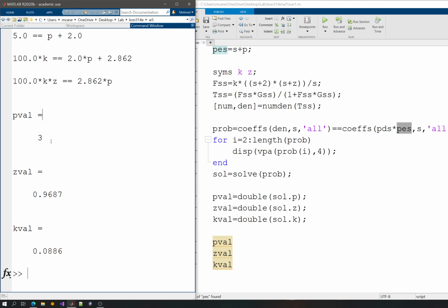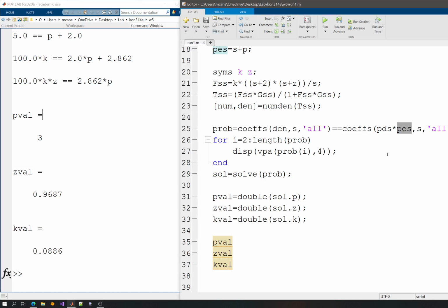closed loop system. It might be possible that p-val is not positive, and then I will say that it is not possible to use this design method, or I should maybe update my time specifications. Maybe I should choose a different or even slower settling time, or a higher value for the overshoot. I should maybe let the system relax a little bit more. I am forcing the system too much with this control structure, since it's not possible to achieve that. It might also be that the controller is insufficient. I might change to an upgrade to a different controller structure, etc., etc.